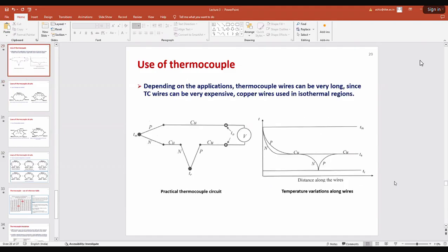Okay. So my understanding is that the voltmeter is part of the data acquisition system. What the lab instructor was doing is he just put one of the ends of the thermocouple into the machine and it was able to measure the temperature, but it was not at the direct point of contact of the pin and the disc.